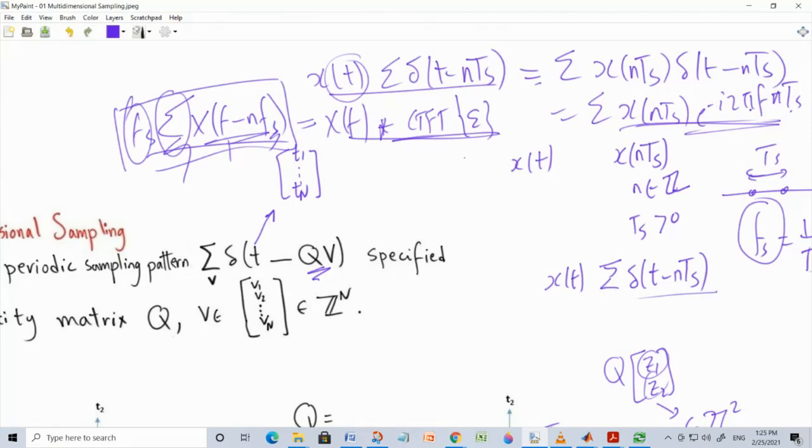So once you sample in time, you convert the signal into discrete. Then your spectrum, the CTFT of x of t, now becomes a DTFT, and it is periodic, and it has this specific form. It is the original CTFT, but now it is shifted at all integer multiples of the sampling rate, and then it is added, and then it's multiplied by the scaling factor Fs.